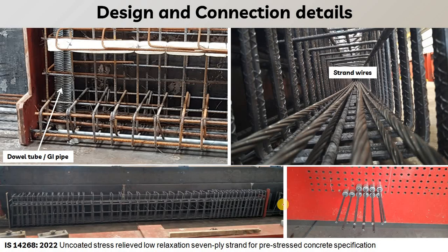Now let us see how precast beams or prestressed beams are casted in the factory. What is the process? So here you can see this is the prestressed element, where these strand wires are used. These strand wires are placed in profile as per the design drawings, and here you can see this is the reinforcement cage that is placed in position, and then the wooden side shutter that is used for side shuttering purpose, in which both ends will be closed.